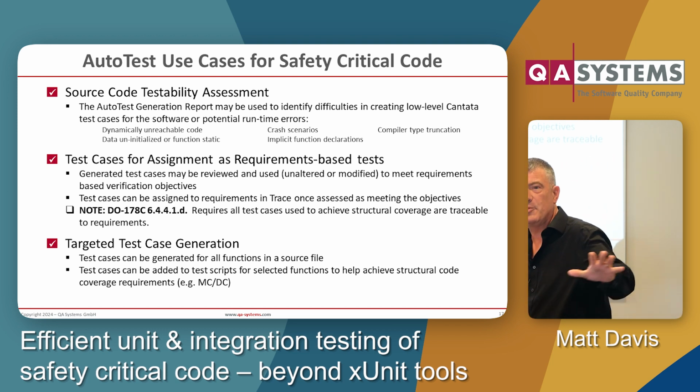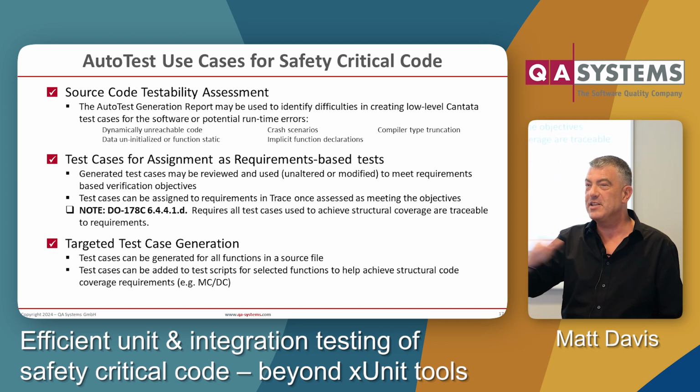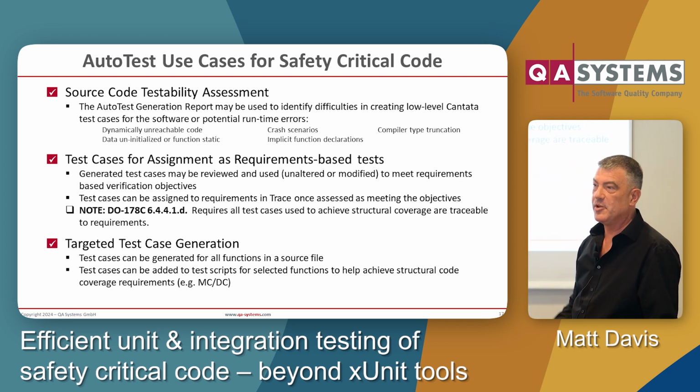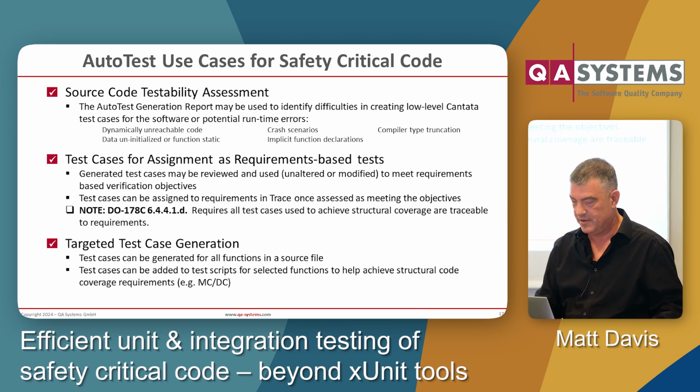Some standards, nobody working in avionics here? Good, you're fortunate. Some standards like DO178C, the avionics standard, says every single test case, no matter how or why it is used, has to be traced as a requirement-based test. You must define a requirement for every single test case.